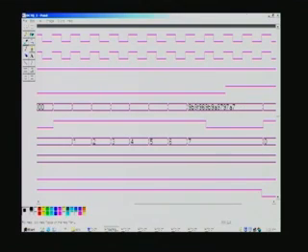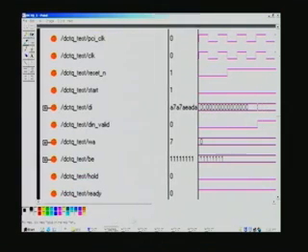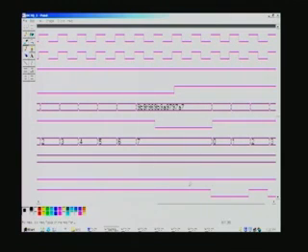You can see 16 digits of hexadecimal. So, once data in is withdrawn, after a while only it will be written here, and this signal is the ready signal that you have at the bottom. So, it is normally ready, and then when the first data is written, temporarily it will be withdrawn and once again asserted when counter is 1, which we have already seen in the design.